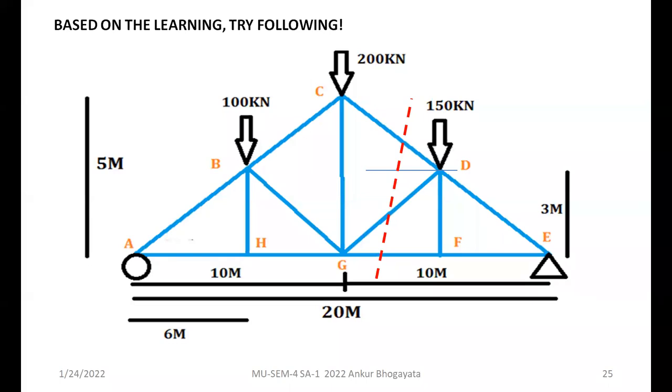That is the advantage, I would say, the positive side of the method of section, that you practically don't need to remember earlier work. As in the case of the method of joints, you have to keep track of all the forces which were calculated earlier, including their sign and their nature, positive or negative, and keep everything in your mind while you run from one joint to another in the analysis. On that point, the method of section doesn't occupy your memory as much, right?